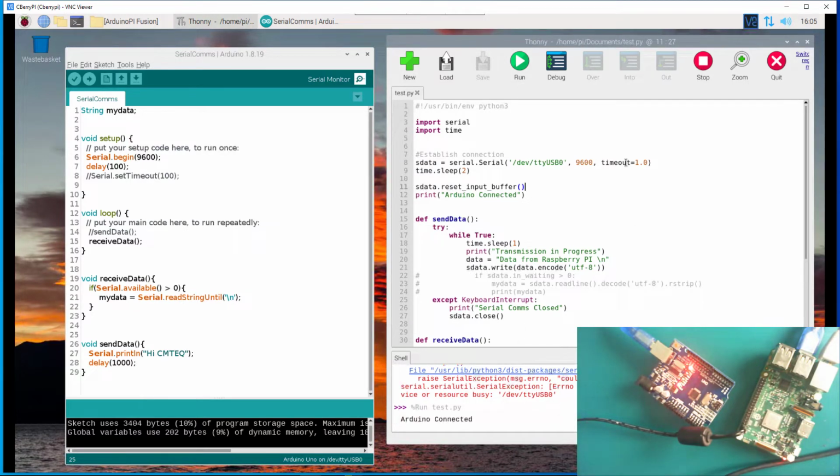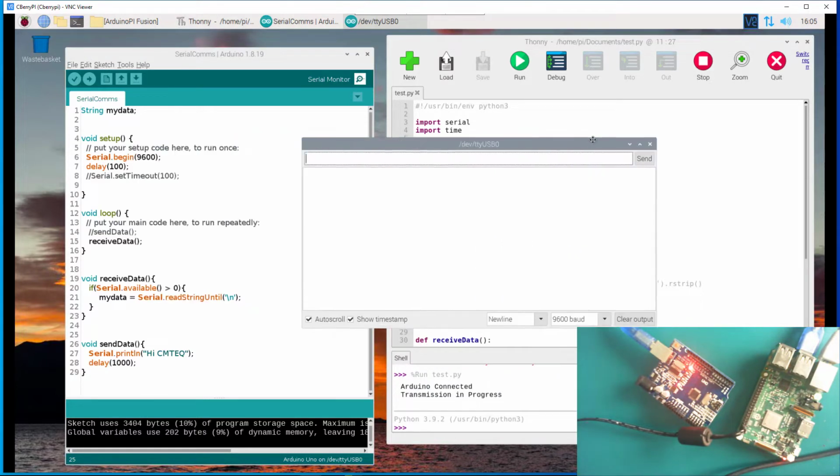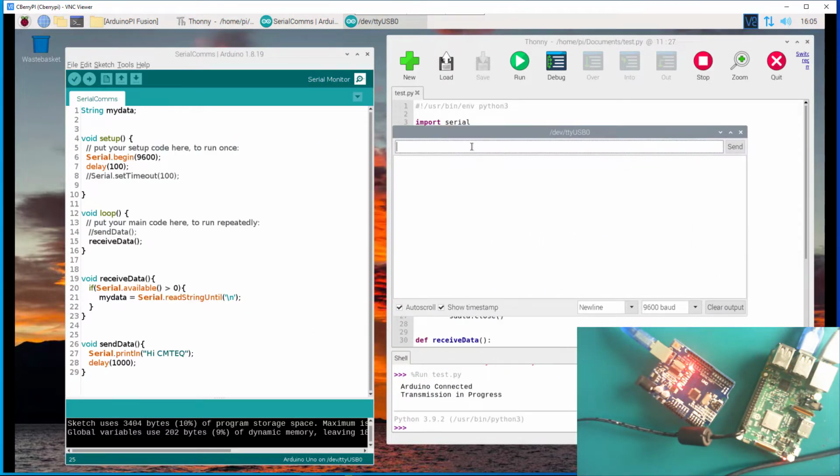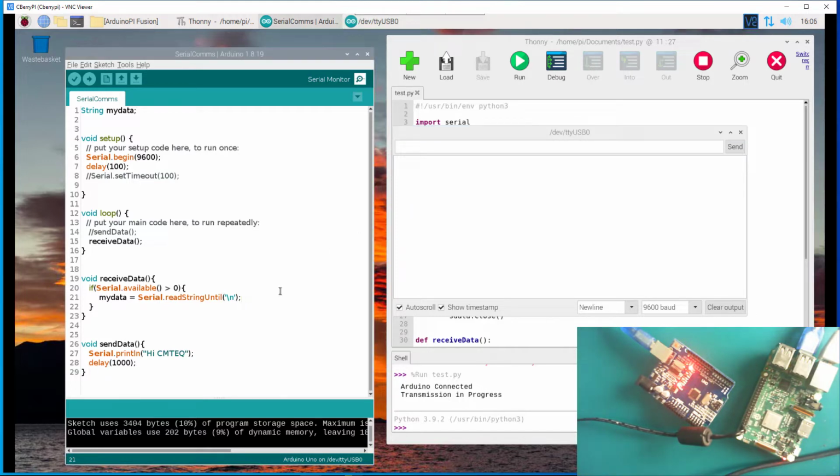We saw that in the previous tutorial. Now, even though I have the serial monitor open, I can send data via this window. If I type test and send, I'm not seeing what I'm sending. It should appear here. Why? Because I do not have the serial print line of code here. So I have to include that here. I'm then going to include the serial dot print line.